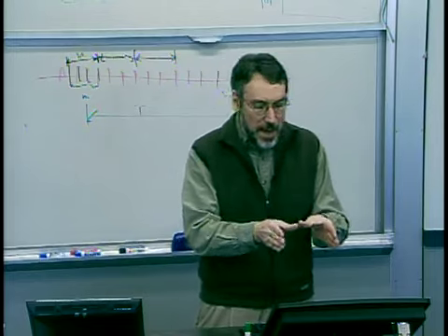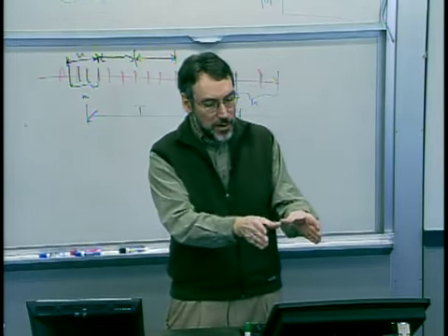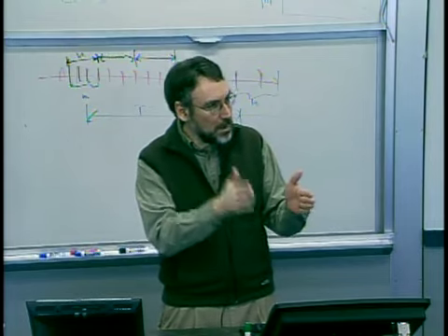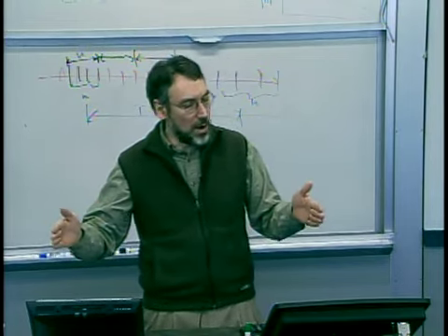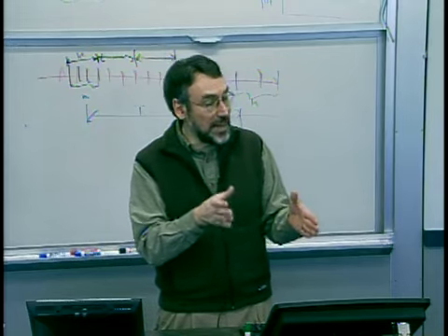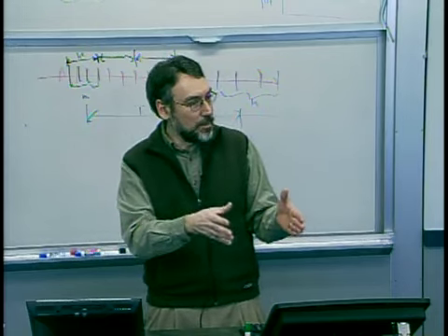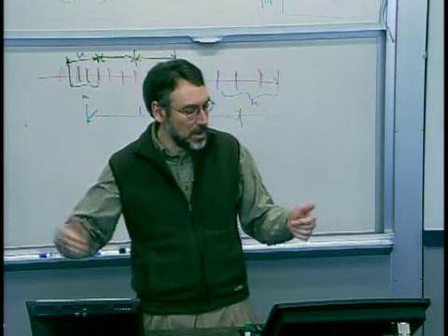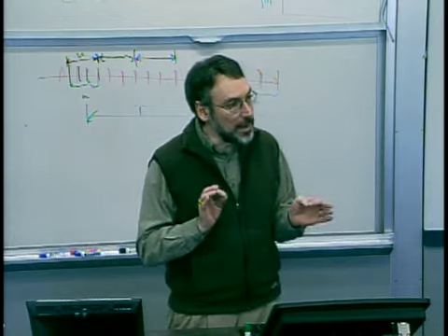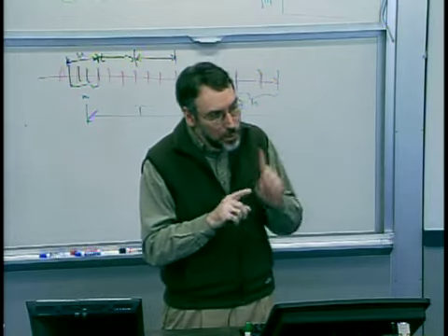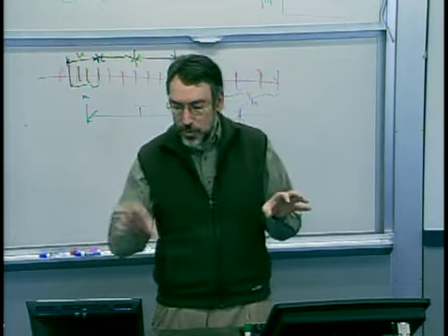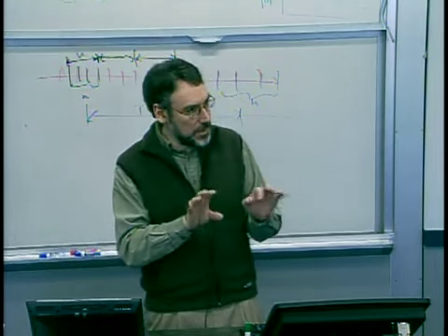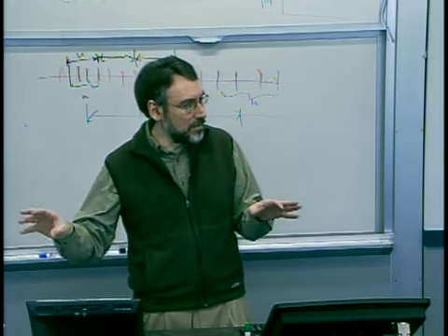And yes, indeed, there is also very often the question about quality roll-up, of how quality loss or deviations either add up or compound themselves across multiple steps. So we'll talk about that. But the first quick answer there is, if each of those process steps are independent, then it's simply an additive function.